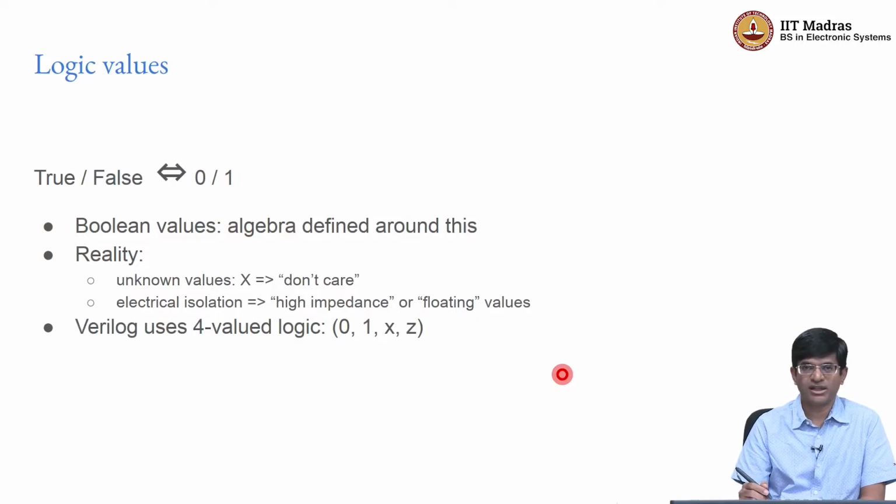In the context of logic modeling with Verilog, it's actually more of a don't know rather than a don't care. So what you are saying is that an x is an unknown value, right? And you use this to say that if I have not specifically initialized a particular signal to either 0 or 1, there is no way that I can predict in general when I switch on the system whether it is going to be 0 or 1. And this is an actual practical matter, right?